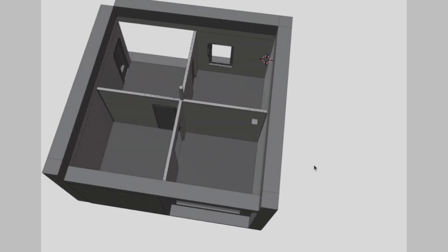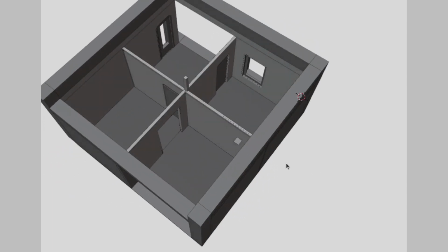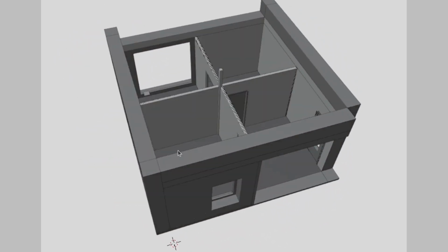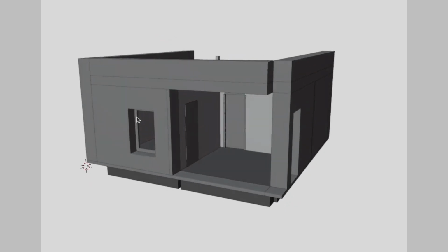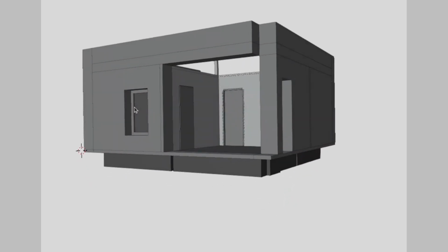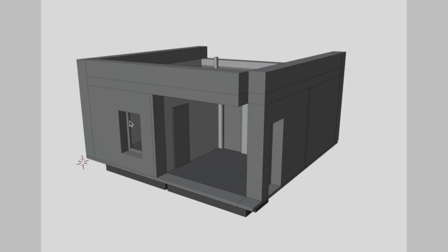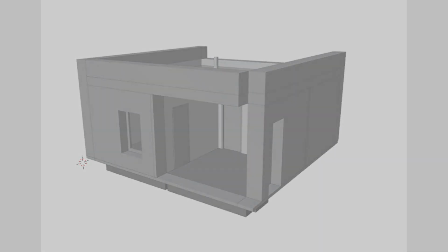My experience says that these rooms will require minimum heating and will have a tendency to retain heat from solar and internal heat gains, but that these are likely to be managed by natural ventilation or the occasional mechanical cooling system. For this study, which is focused on the impact of unintended air movement, the model will not include the usual MVHR kit or operable windows.